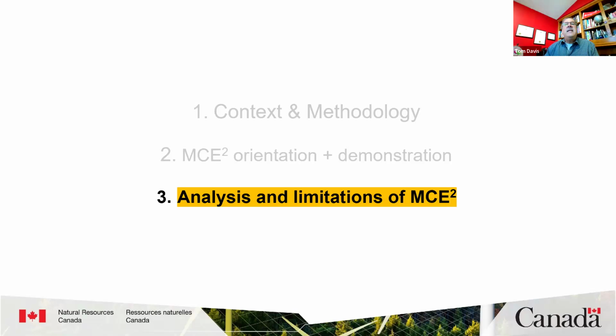Are fully insulated vertical walls adjacent to roof areas, attics, calculated? So again, it knows it's a wall. It knows that there's an attic above it. So it would do those R value calculations for the wall. In the attics, especially in retrofits, if you don't have stepped trusses, what we found to get the R60 above the exterior wall assembly is that we had to go with a 2-pound foam for about a 2-foot perimeter around the exterior of the house inside the attic to get that R60 value.